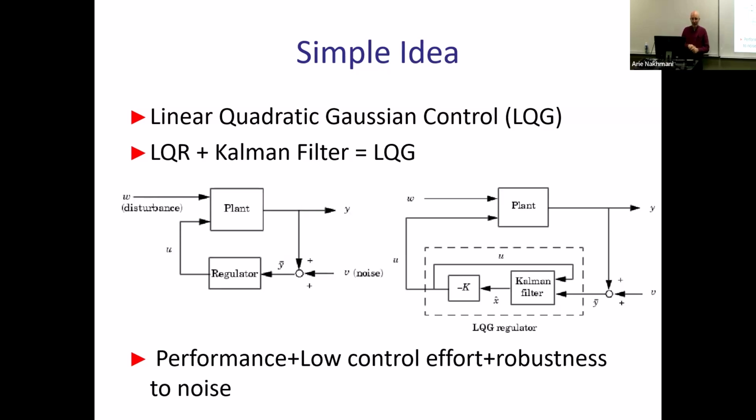By that connection, we know that we will improve performance of the system, so we'll handle low control effort because we are weighting that with R matrix or rho, right? So we can reduce the control effort. We can converge all of the states as fast as possible to the correct state and then to minimize the energy of the states, which means they all will go to zero as fast as possible, optimally in LQR, right? And also it will be robust to noise and disturbances because we are using Kalman filter. In a way, Kalman filter is just low pass filter of some kind. So it kind of cleans some noises in the system in real time as it goes. Okay, so it estimates noises and cleans them, ignores them, because producing the mean possible value, most likely value, highest likelihood value for your output, okay, for estimated X.